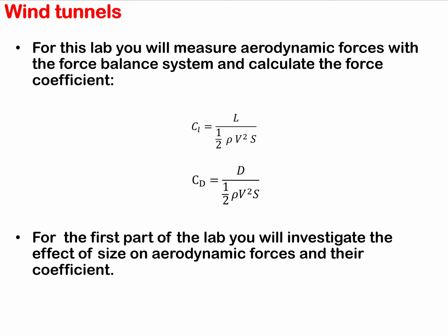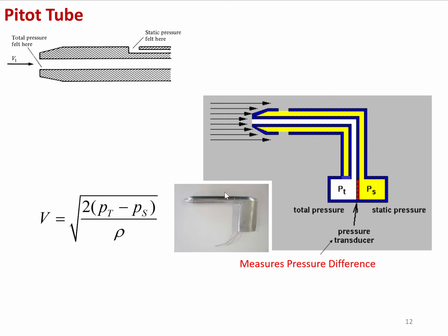It has to be the same vehicle, same geometry, at the same flight conditions. So the idea is, again, flow similarity. As long as you keep the flight conditions and the geometry the same, size does not matter, and lift coefficient and drag coefficient remain the same.